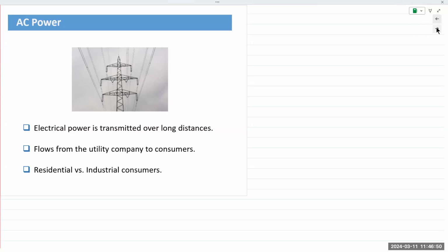Well, it's important because inductors are energy storage devices. Energy flows into an inductor. If you apply an AC voltage, the energy flows into the inductor in one half cycle. In the other half cycle, it flows back out, right? If it's a resistor, energy just flows one way and that's it. It might flow in and out, but it does not store any energy. For a capacitor and an inductor, it's different because they're energy storage devices. When you apply an AC voltage or current to an inductor or capacitor, the energy flows into the device and then it flows back out into the circuit.